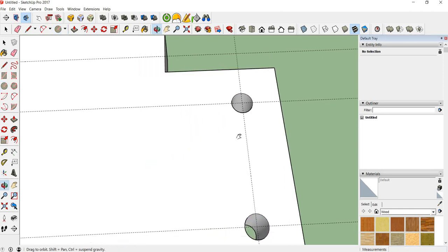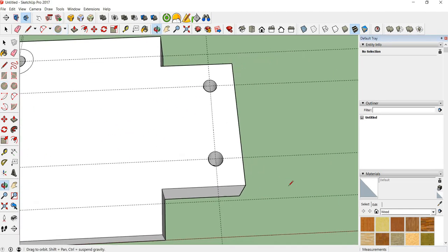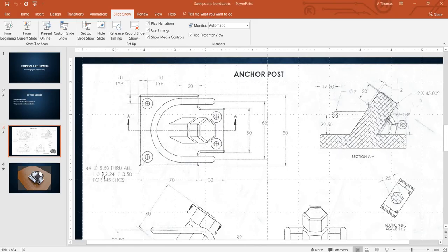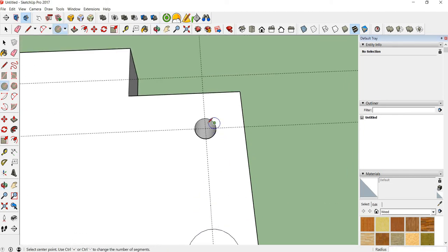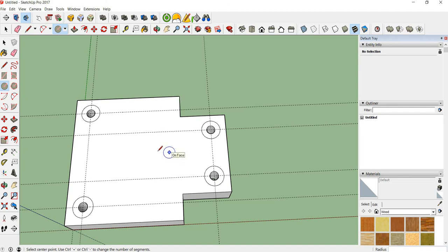One thing I want to show you guys is if you put your holes all the way through like this, now remember these are diameters, so SketchUp works with radiuses. If you go here where it's an X, you can see how it's just kind of an elliptical shape. Hit the up arrow and that'll put that there, then type in 6.12 for that, then up arrow, and then you just slide it until it says it again and it will automatically lock.